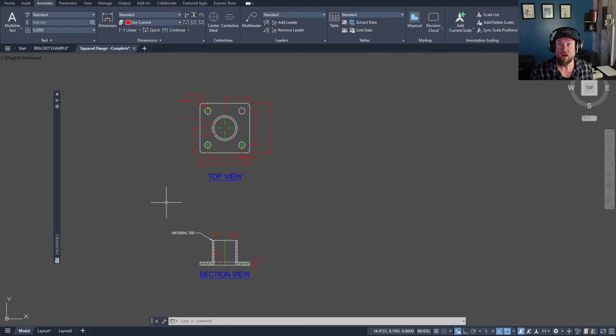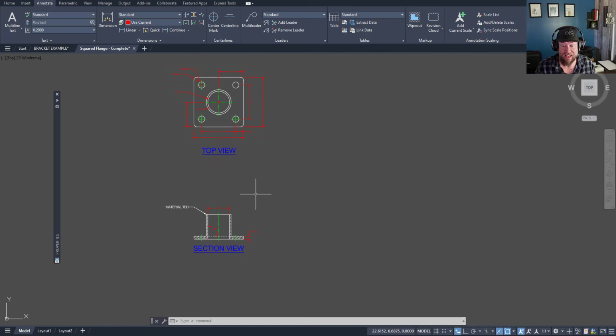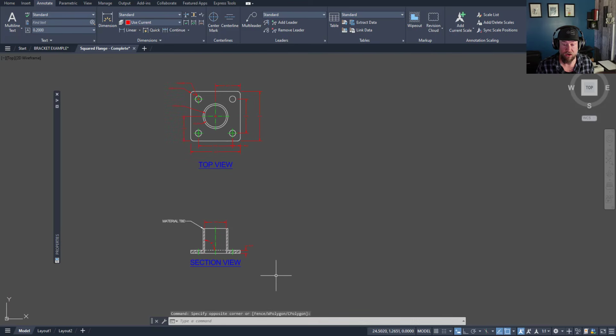Let's get started. Alright, so one of the easiest and earliest tips that you should learn when working in AutoCAD is that of typing things into the command line, and not just typing in the commands, but memorizing the shortcuts. I've got an entire video on 20 of my favorite shortcuts, but I'll explain a few in today's video. Almost every command within AutoCAD has a shorter shortcut command that you can type into the command line.